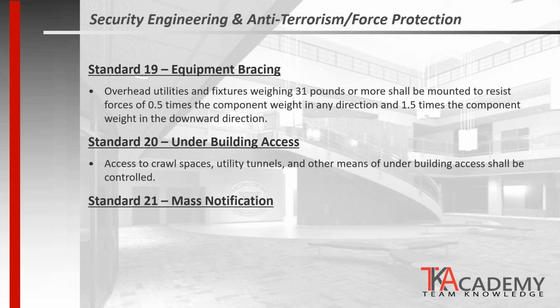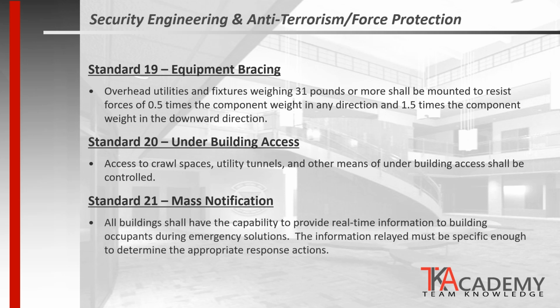Standard 21 is for mass notification. All buildings must have the capability to provide real-time information to building occupants during emergency situations. This information relayed must be specific enough to determine the appropriate response actions, and legible enough that the message can be clearly understood. Mass notification systems are typically integrated into the fire alarm systems within a building.